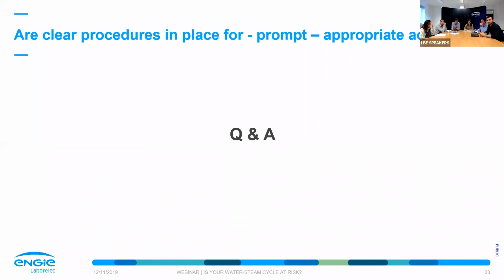So you can always create standstill corrosion. It depends also on the pH that you apply. If you apply an extremely high pH, like 10.5, it's definitely okay. But when it's a pH of 9 to 10, you must be very careful if you have a long-term shutdown to keep the situation like it is.